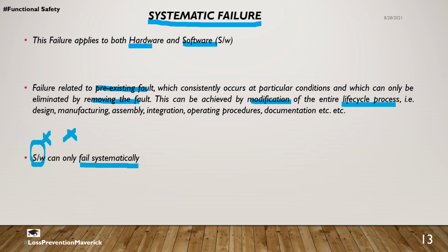What this means is that, let's say the system integrator writes the program for a particular PLC, and if he makes an error or there is a bug in that software which is not verified or validated, and that software is copied onto a particular PLC, and this PLC is then mass manufactured, that one systematic failure alone now guarantees that all the PLCs which went through that assembly series will have that bug. So this is called a systematic failure.